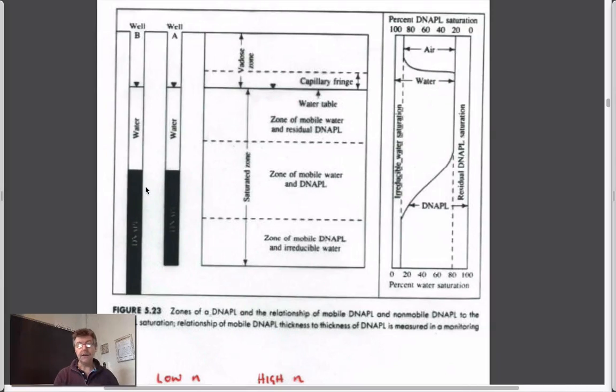And it would be this. You drop it into the aquifer, it settles down to a capillary barrier. If the capillary barrier happens to be here, it will go all the way down to this. If the capillary barrier is here and your well bore only goes down part way, then it won't register the part that's below this. If your well bore is less than another well bore, then again it will truncate it at whatever maximum depth it is, obviously. But if you look at the distribution of these as you go down, then this would be exactly what the DNAPL would look like.